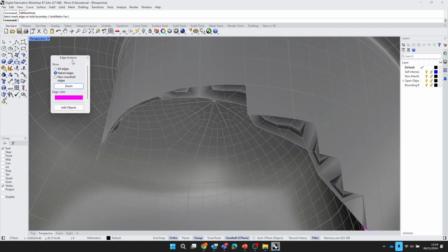Now, for those of you that have worked with SketchUp files before, if you've brought your files into Rhino and they've looked like this, where it does weird reflections on edges and stuff, you might be familiar with a view like this. That's what we call flipped normals. In SketchUp, you get slightly different colored faces depending on whether it's an interior or external face. That's essentially what this is doing. It doesn't know whether this is facing inwards or outwards. So what we want to do is rebuild the mesh and tell all of the faces to point in one continuous direction, outwards, effectively.